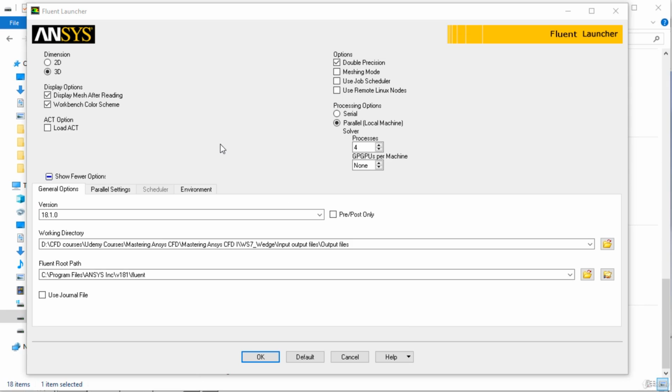And here I've just launched Fluent from the start menu, and here I can choose a working directory, which is D here, and it's a 3D solver, and you can choose double precision if needed for more accuracy. And it's a parallel version, and I will use all the 4 cores because this has 1.3 million nodes or around that, depending on the number of nodes you define on edges.